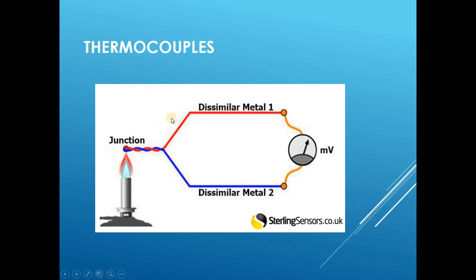Gentlemen, this system works on the principle of thermocouples. Two different metals are joined together and placed in different areas. One is a hot junction and one is a cold junction, and EMF will be induced when this is heated. Two dissimilar metals are joined together to a millivolt meter. You will get an indication. In the aviation field, this is the major application.